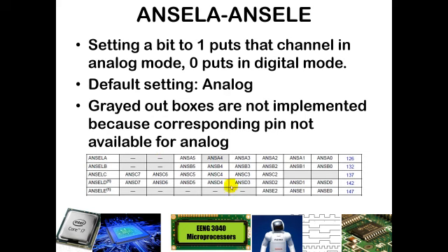Down here, RE3 is not available for analog mode because that is where the master clear is set up. That's where our reset switch is connected. And then additionally, we have 2 pins in port C and 2 pins in port B that are not available for analog mode.